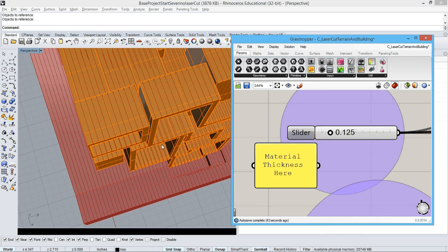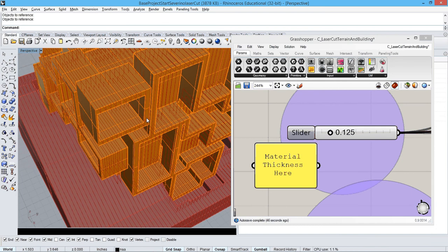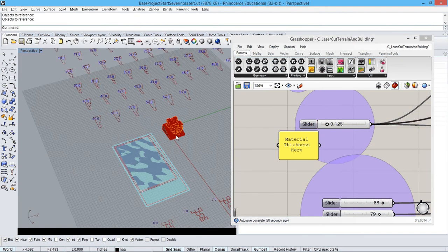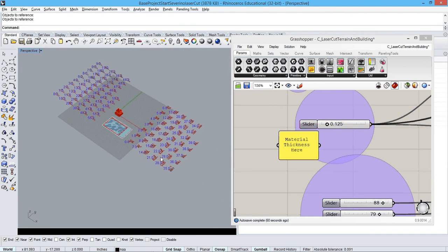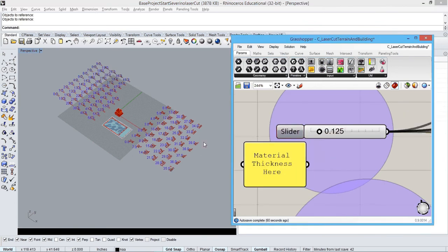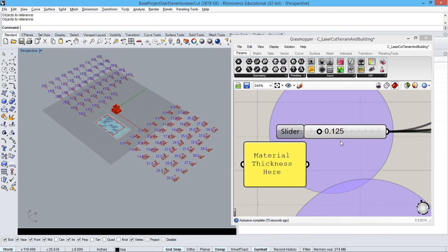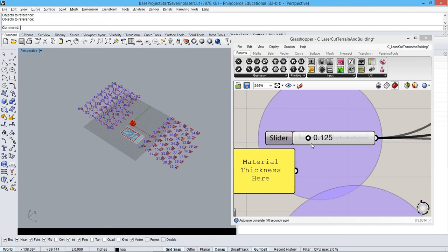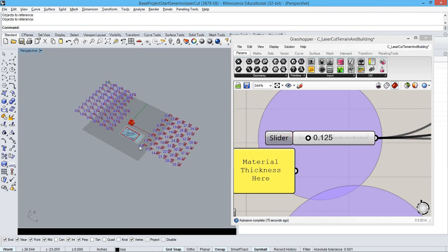Now if you go to buy some chipboard and you find a better one, you can easily double click on the white area and set this to a different number. I encourage you to search for this thickness. Lower, it's going to create a lot of cuts for you, but it could be better definition, and thicker, you could have a bit of trouble to laser cut it. But again, you're more than welcome to change this parameter, and obviously the thinner the material, the more cuts you need, therefore the more time you need in the machine.